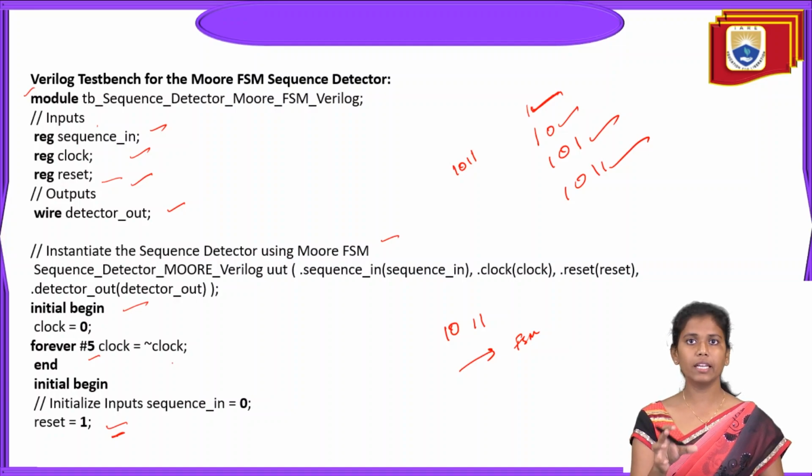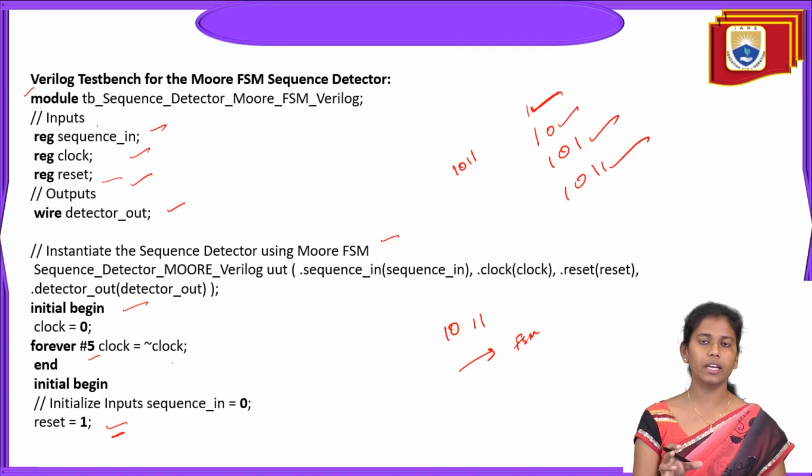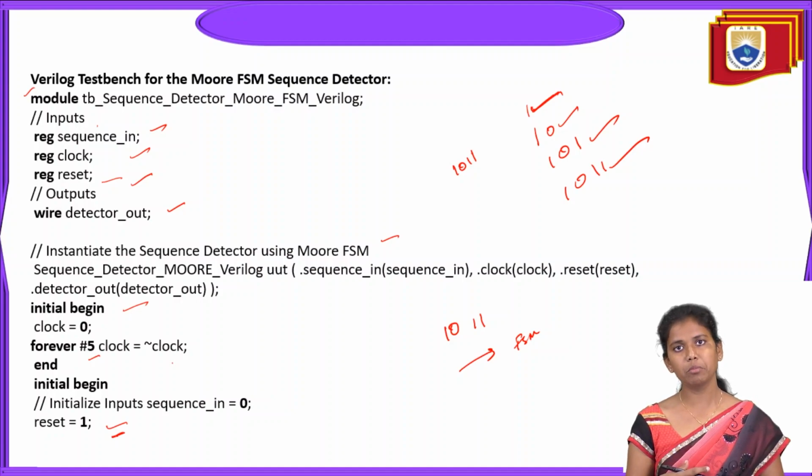You can write inputs and outputs easily based on the circuit diagram or the block diagram that you have mentioned. From the block diagram, initialize the inputs, outputs, and then what is case sensitive. In which language or at which level you are going to write your code: if it is behavioral modeling, then remember always at the rate; if it is data flow or gate level modeling, remember assign, by using the assign keyword.